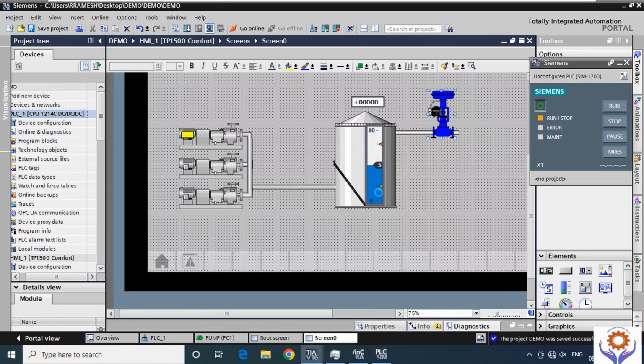In the second part we communicated between the PLC and PCs, and we covered some troubleshooting points for the communication issues and also for the Modbus communication between the PLC and simulators. And we also made the basic design for HMI panels, took the tags from the PLC and integrated them with the HMI, and we made the simulation of the HMI panel also.